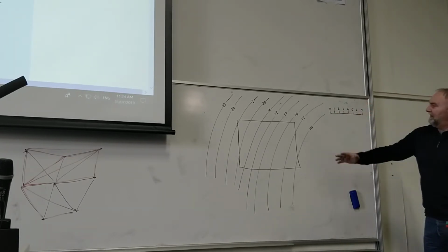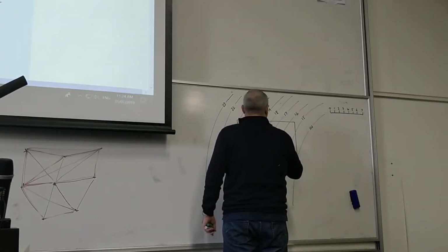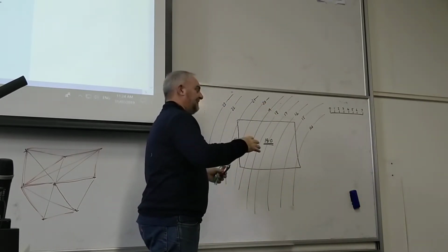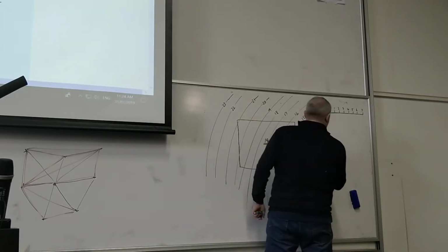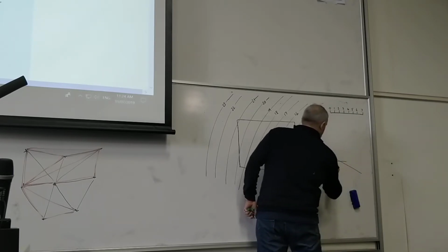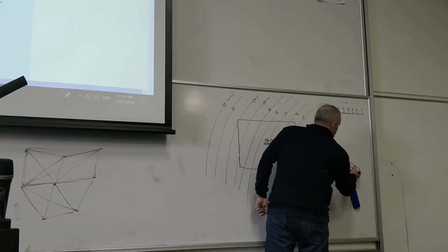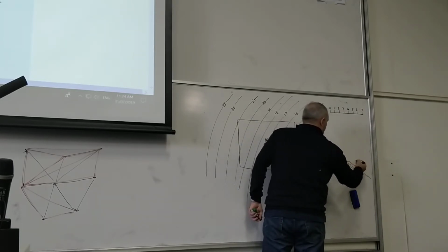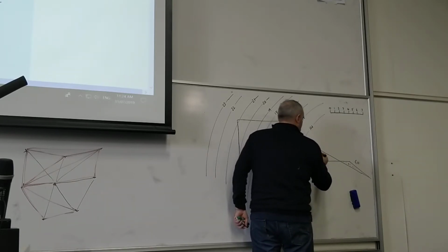So we've got a platform, we've got to give it some sort of a, let's say, it's sitting at 18.0. So we're lowering, let's pretend it was a massive piece of metal, and we're lowering it into a bank. The bank looks like that, and we're putting this platform in like that. Some of it's going to dig into the bank, and some of it's going to come down and be supported by fill. That is fill. So this end here will be fill, and that is what we call cut.